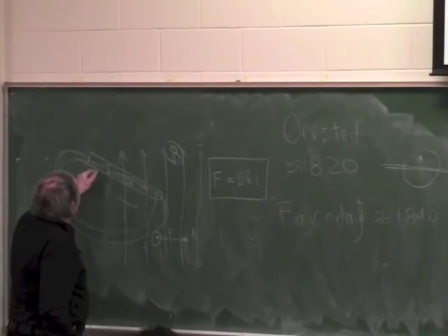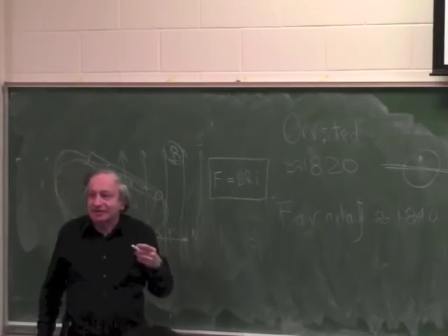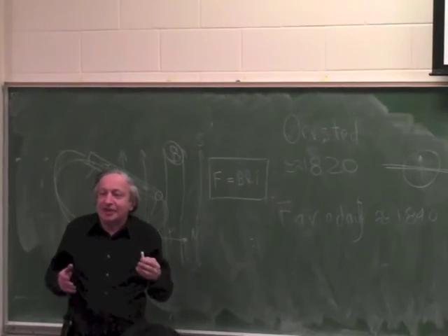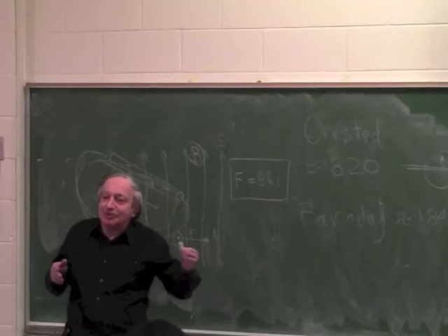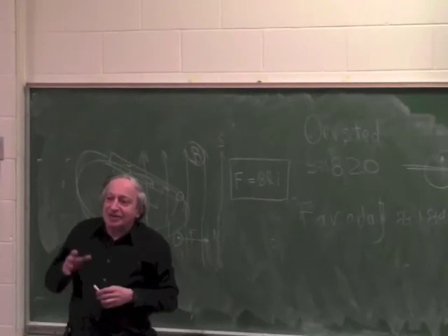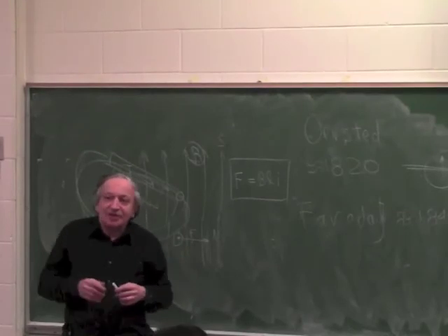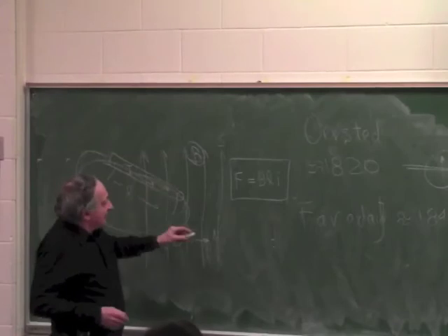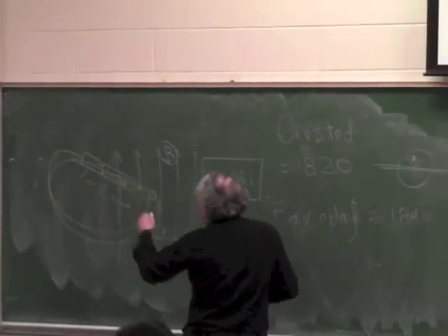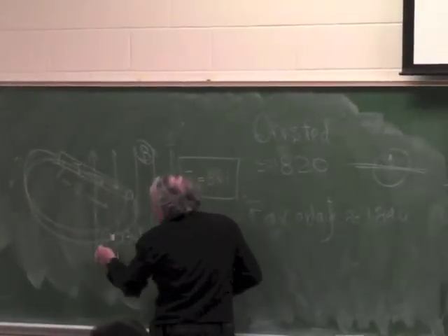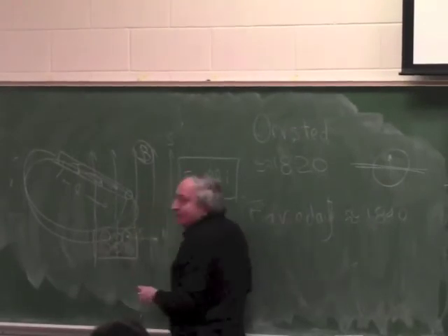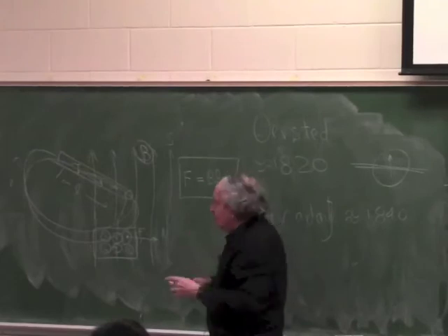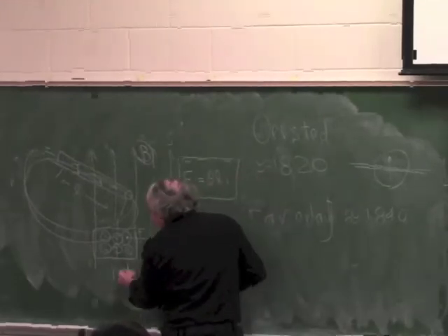you are putting many units of L in parallel, right? So you can explain it two ways. Either you can explain it, you're making the effective L longer by putting many units in parallel, or the easier way to understand it intuitively, you're making the current bigger. Because if you wind the coil with many turns, you end up with many currents, and they all appear like one big current equal to Ni.